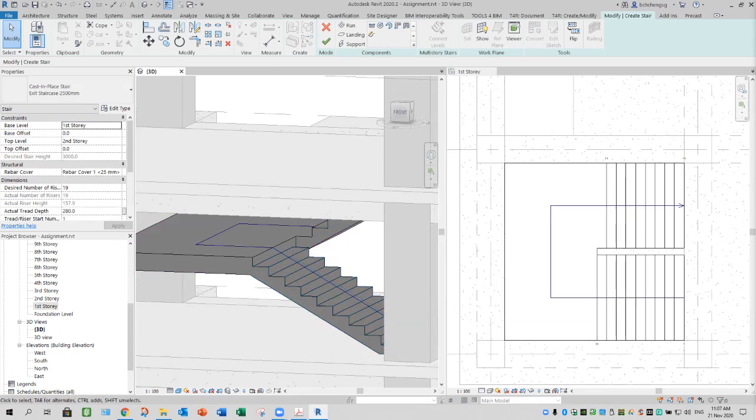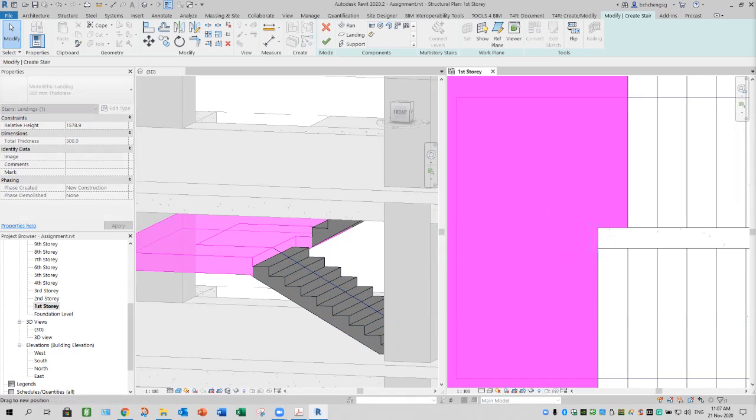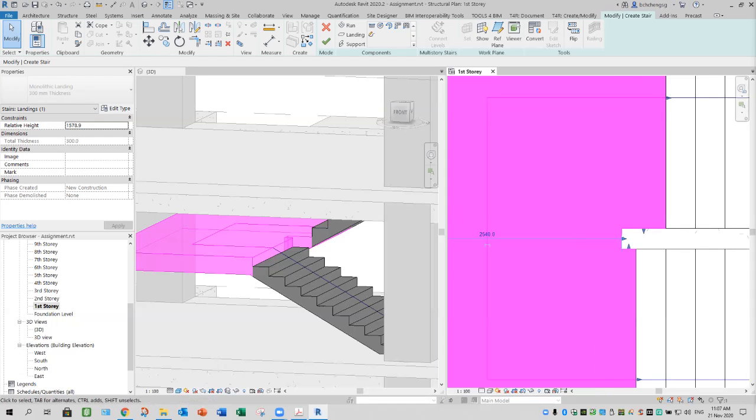So next thing I want to change is this, which if I'm going to select again, nothing for me to adjust. Hopefully here can. If I drag this, this is what I want. Good. If here can adjust what you want, then it's okay. If you can't, you got to go convert and do the sketch based editing. So sometimes staircase might not have this intelligence. Then you got to do a conversion to sketch base, which allows you to have more adjustment, like some curve shape and so on.